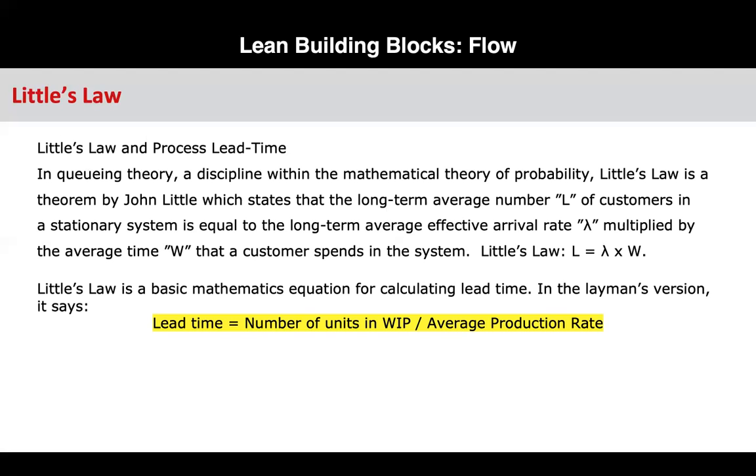If we had one piece, a WIP of one piece, like a unit load of one, and the average production rate was one, the lead time would be one. But on the other study we also have to factor in the material handling time. The importance I want to share here is that the amount of WIP, or the batch size, definitely has an impact on the lead time.